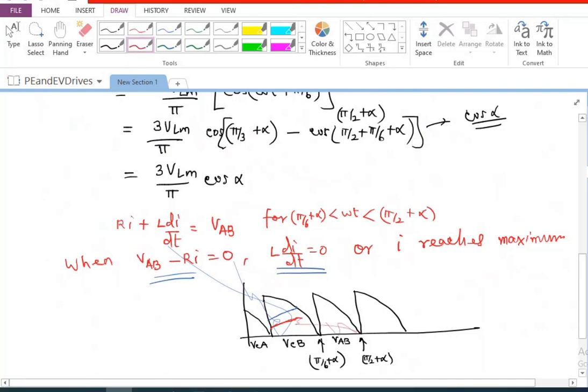So current is going to decline like this. Then again it will increase, then it will decline like this. So you are going to see that the current has a waveform somewhat like this. This is how the current will be for RL load, because the exact equation, whatever we wrote earlier also, is very much valid even in this particular case.